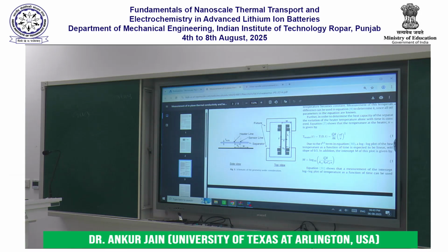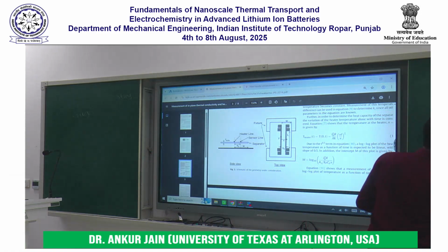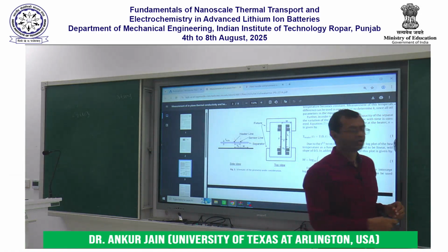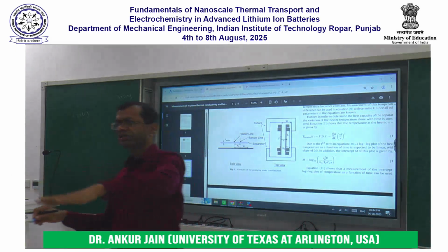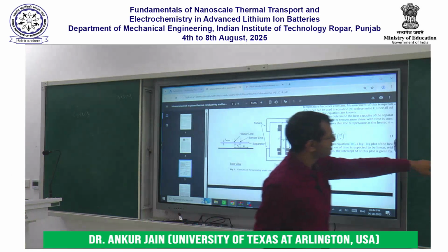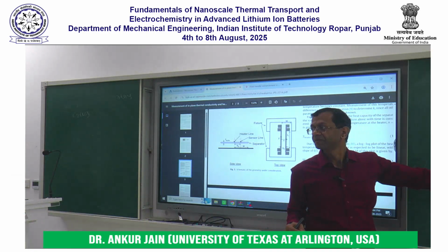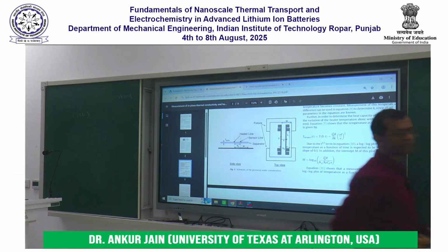What is typically done is that you take the substrate, you put a mask on top of the substrate. So imagine if I take an aluminum sheet and make a hole in that sheet that corresponds to the shape that I want to print, right? And I place this mask on top of the substrate, and put this in a metal deposition machine.